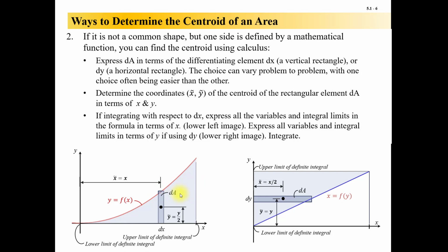You just need to be able to draw this differential area. There's usually an easier element, meaning vertical or horizontal, to use in one problem than another. That's what I'm saying. The choice can vary from problem to problem. And even between finding your x bar for the problem and your y bar for the problem, you could use a different element for the two different calculations, because you basically just run the same calculation again. You'll see it in a second.